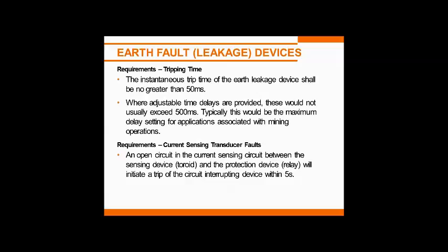The standard says that you have 5 seconds in which to make that decision, and that time gives you time to get away from any false trips or any slip ring sort of problems that may occur, or any small variations that occur. You've got a little time to make that decision.